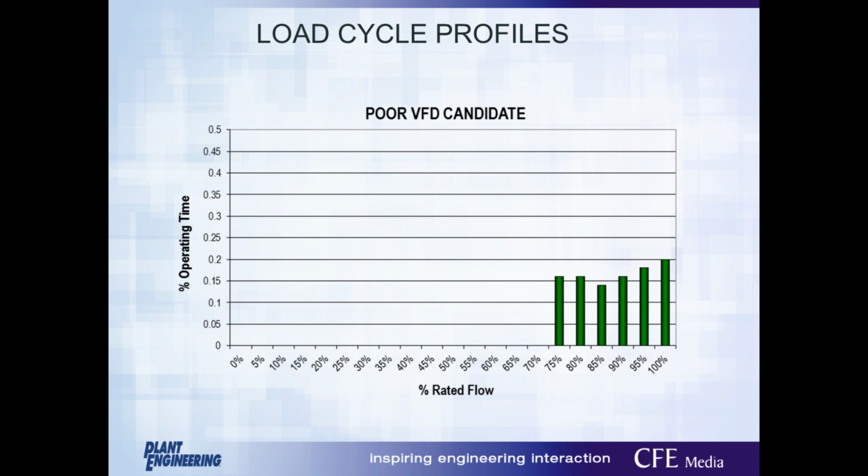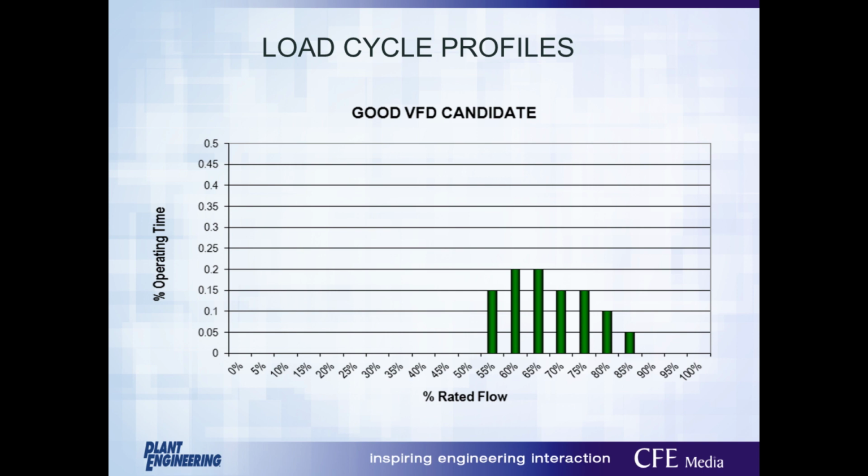So next, we're going to look at 3 different applications and compare the validity of adding a VFD. First, we look at a poor VFD candidate, a very highly loaded application. You may ask, why shouldn't we add VFDs to highly loaded applications? The VFD itself does use some energy. If you put a VFD on a motor and the motor is running near full load, you're just going to add unnecessary power to the circuit and actually raise your electricity usage. So adding a VFD doesn't make sense here.